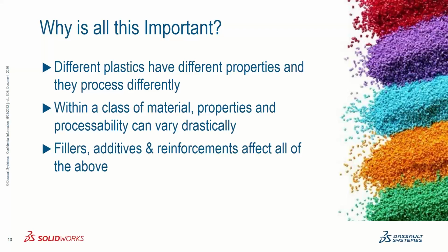Whereas in the case of your headlight lenses, the material of choice tends to be polycarbonate, and that's because polycarbonate, as I mentioned, has excellent impact resistance. And in a car, as you can imagine, the headlight lamps, lenses tend to have lots of objects flying at them, and so the impact resistance is very important.